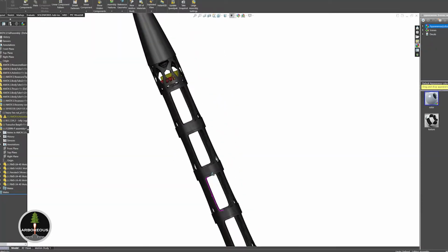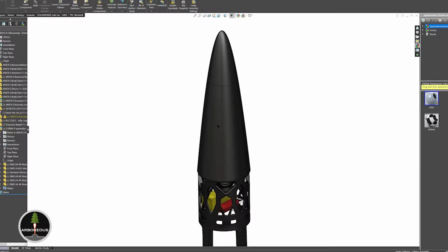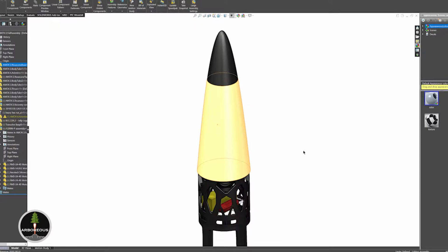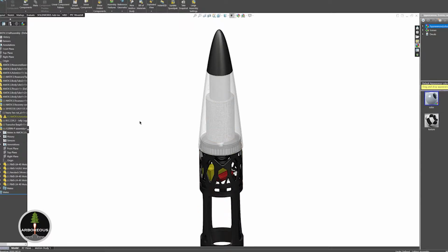The avionics section typically bisects the rocket, separating both the main and drogue chute, allowing for a segmented release. This makes the avionics section the most important part of the dual deployment recovery system, as it retains the shock cord, holds any necessary electronics, and the ejection charge for the main chute.